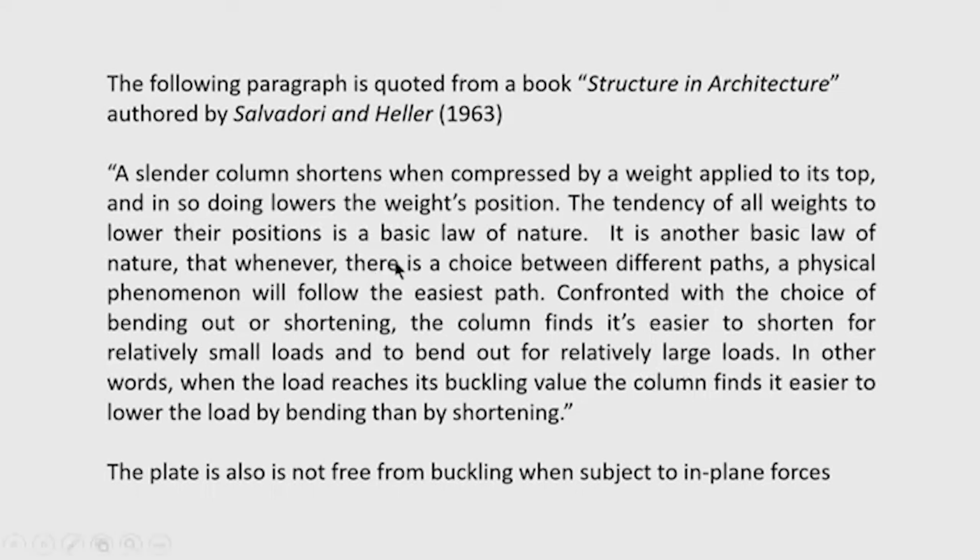Bending will generate large deflection, and the member will choose bending instead of shortening, as it is the easiest for the member. Therefore, the buckling phenomenon is understood as the transition from the straight configuration to the bent configuration. This transition point we have to determine, and this is nothing but the critical load.